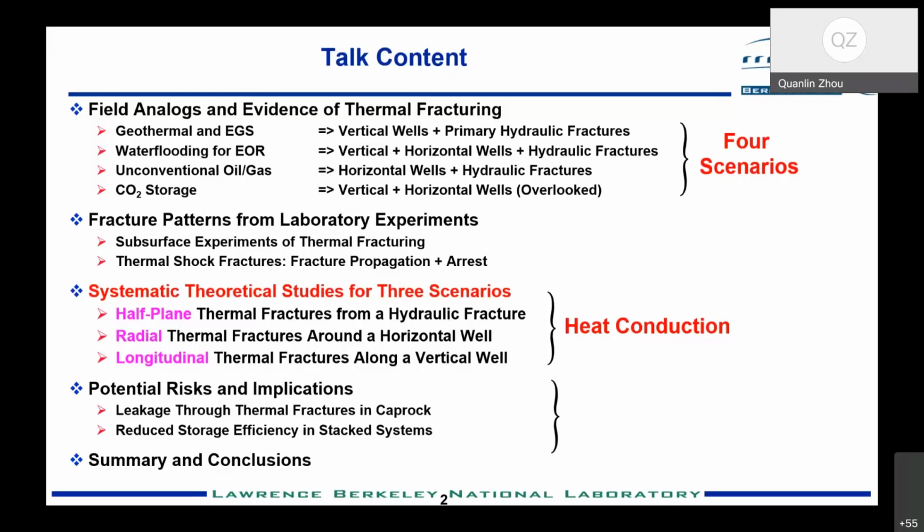Our solutions are good for permitting and fast prediction because we only consider thermal conduction without heat convection. For a site-specific application, numerical modeling of coupled thermal-hydro-mechanical fracturing processes can be used to match field observations.